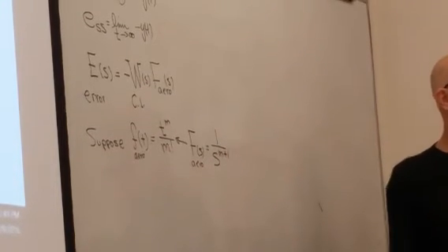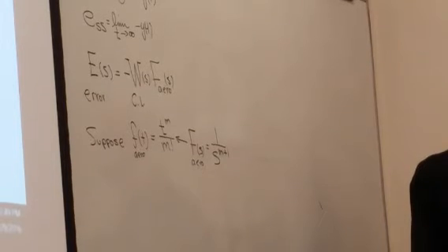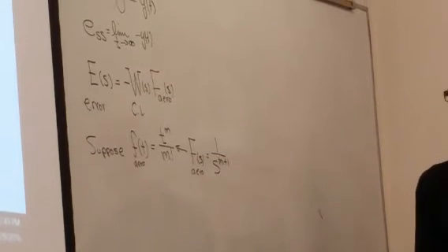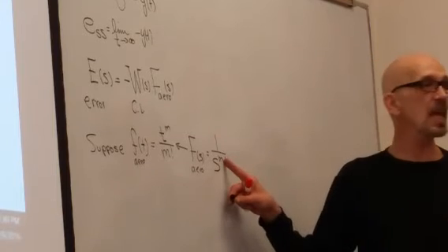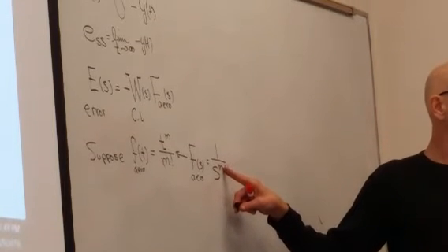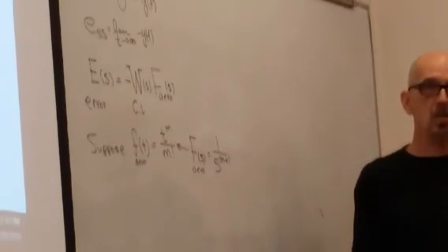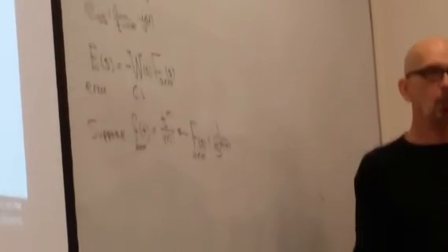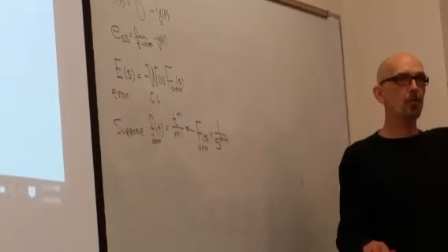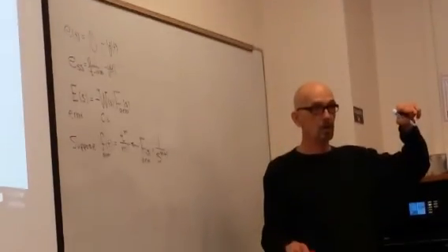Remember, for an mth degree time polynomial, when you go into the Laplace domain, this becomes s to the m plus 1. For a step, it was t to the 0, right? So the step Laplace is 1 over s to the 1. For a ramp, it's t to the 1. So the Laplace for a ramp is 1 over s squared.